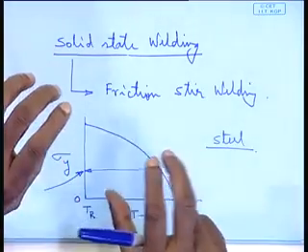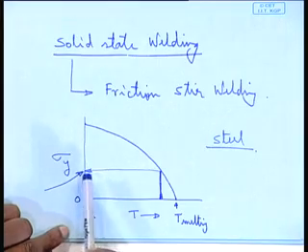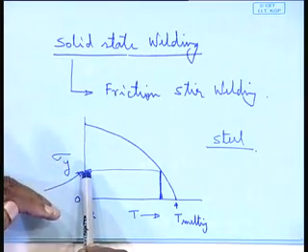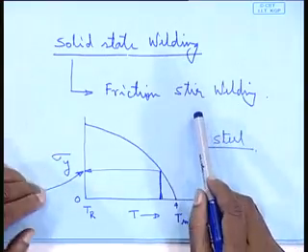Say a steel rod, you want to give it a shape, you heat it up until it becomes bright red, then you slowly hammer. The blacksmith worker slowly hammers it and brings it to the required shape. What is basically happening there? Because of the increase in the temperature, the stress level needed to deform it is much less, or in other words, the yield stress has reduced. So, the same thing is happening here in friction stir welding.